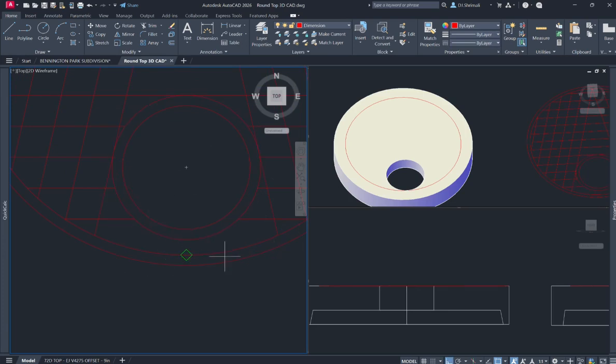So here's the reinforcement layout that we're going to have for this top. Here the rebars are number 5 on 6 in both directions, so you don't have to put a lot of dimensions. When you put the dimension on it, you can just say 6 inches typical. So now I'm creating, what happened is you need to provide diagonal rebars around the opening.